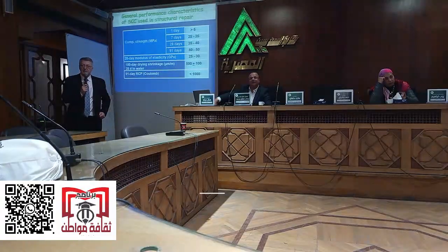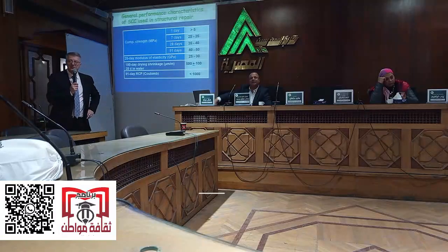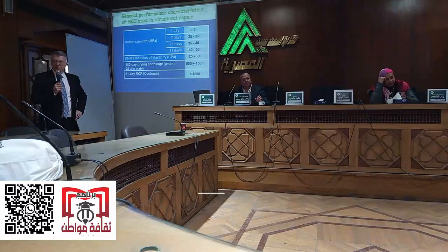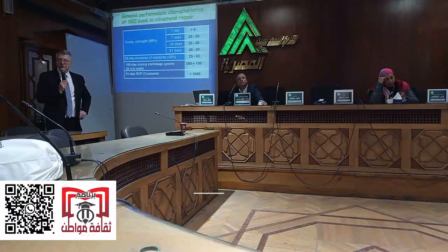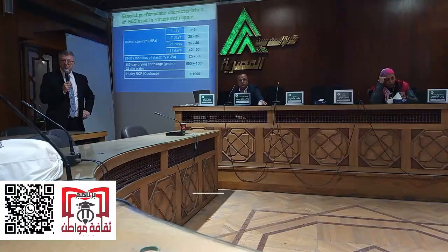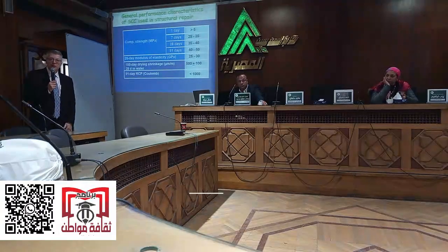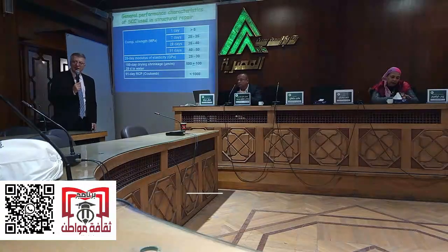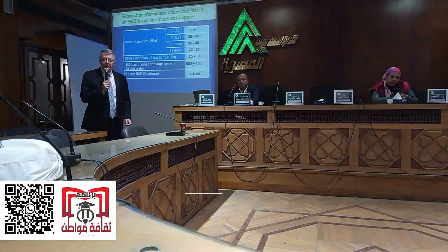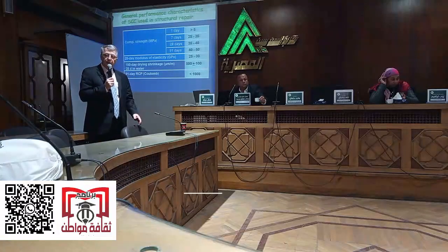But Master, we also need strength in bridges. We need high strength. Of course. Also workability, toughness and ductility, something like that. Of course, you can get all of those. The maximum I see here is 30 megapascal. Yes, it's low on purpose. What's important here is that if you make it very high strength, you don't need it, because the substrate is not high strength. You need a repair material in this case for the durability of the repair itself.